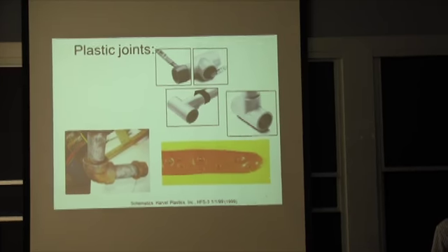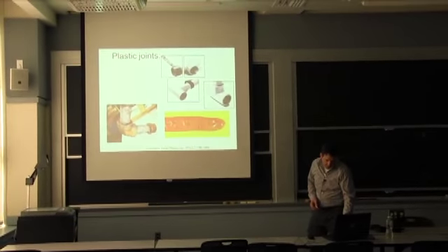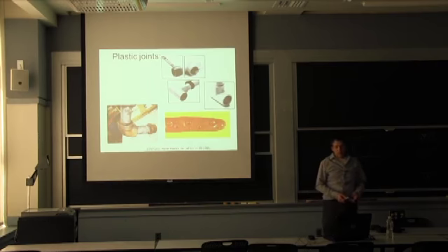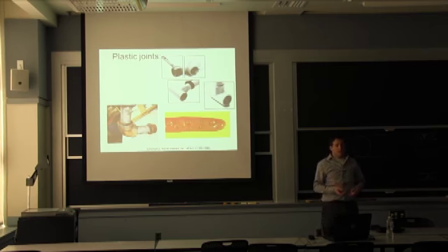Most of the time with rigid plastics, you have these fittings that you apply what we call a solvent cement on. It's essentially a liquid, and you can see it here, the red thing after it dried out. It contains polymers and it also contains solvent. Acetone is a big component, but there are more complex solvents in it.